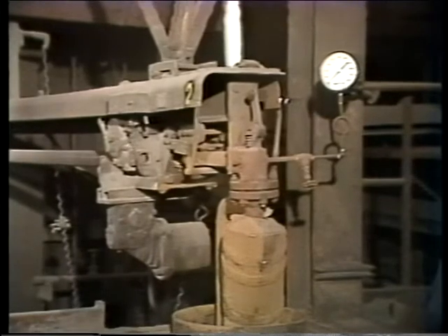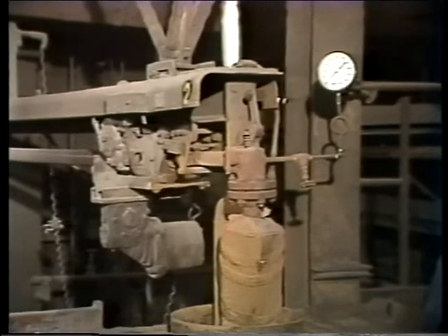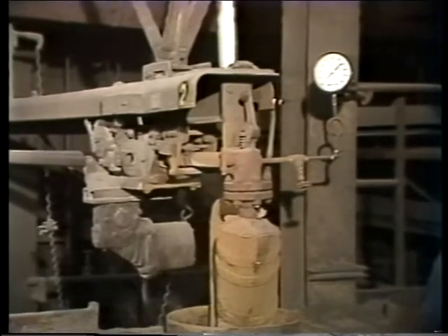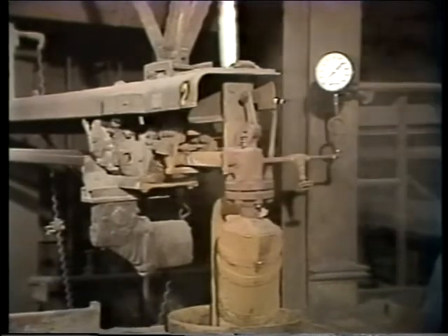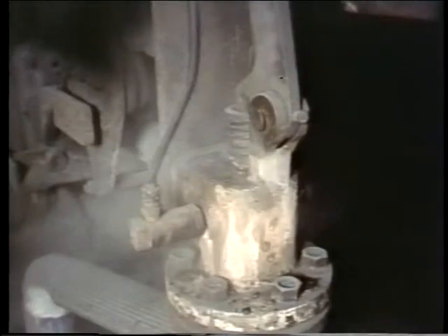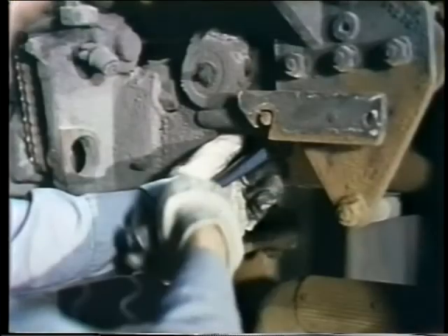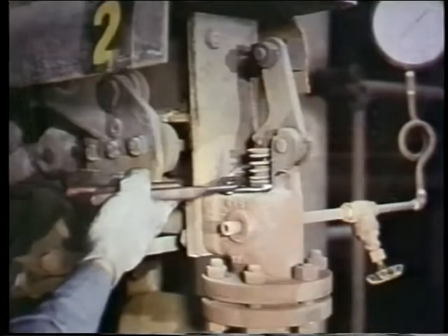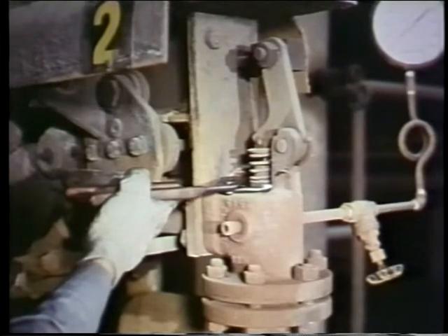Okay, you watch a soot blower through its cycle, and its timing is just fine. But there's a lot of leakage. Packing leaks could occur at the tube packing, like the one you're seeing here, or the valve packing could be the culprit. In either case, it's usually a pretty simple job to tighten the packing to get rid of most of the leakage. Just be careful not to overdo it, or you'll be right back up there to drive home a bound-up blower or cure a valve with a stem that's binding.